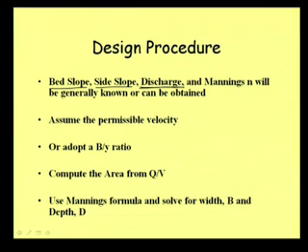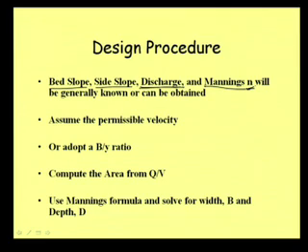So by some means we need to have our discharge, and that part of course we are not discussing in this course. And then Manning's n, that is the roughness parameter. We need to know the roughness parameter from the characteristic of bed roughness and the characteristic of side roughness. In many standard books, Manning's roughness values are available. That part we did discuss in our discussion regarding uniform flow, so we are not discussing it here again, but we can have this value from standard books, and many references are there.